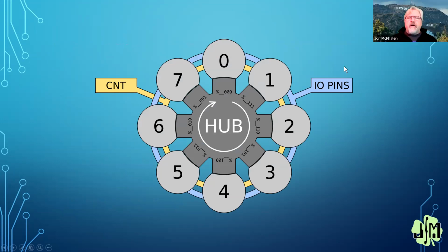Here's an update of a diagram that I had last year. Chip has a really cool animated version of this, but here's the thing to note. In the P2, let's say a cog wants to write several values into the hub. Once it gets synchronization with its initial value, it can write on every clock cycle.